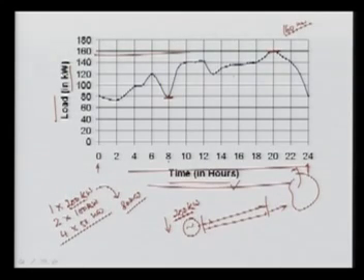Another problem with one unit is that if this unit fails, if there is some problem in this unit, you will not be able to supply even a single kilowatt of the load. So it has less reliability, and since it is lightly loaded for several hours, the efficiency will be less, so the cost of production will be more.